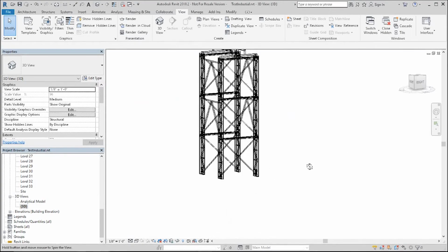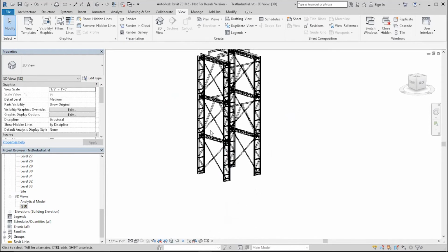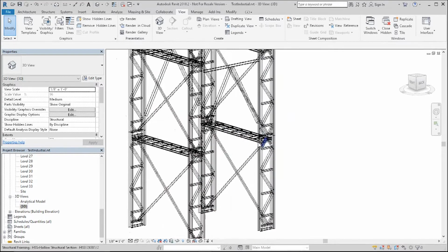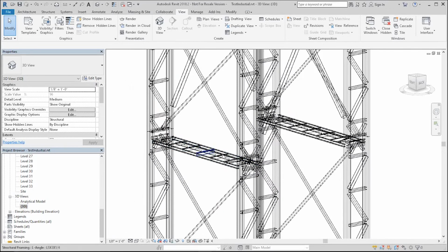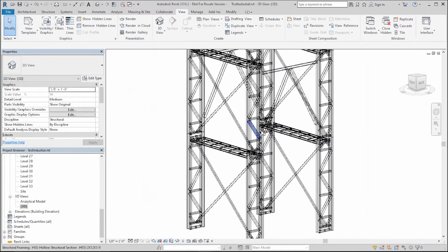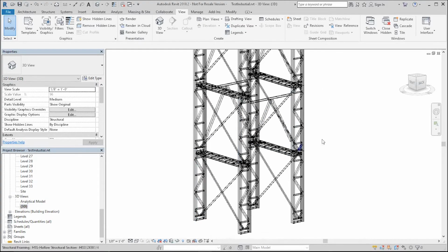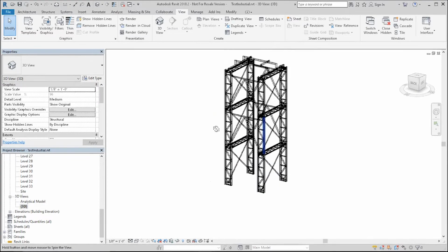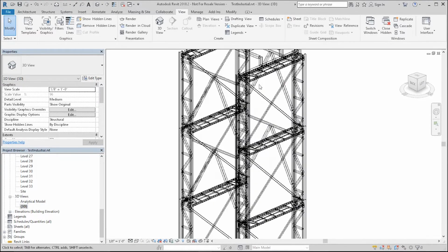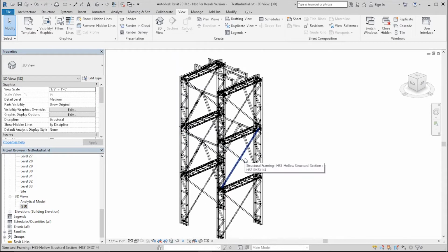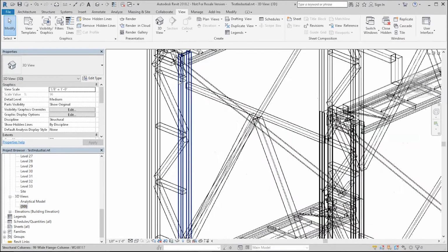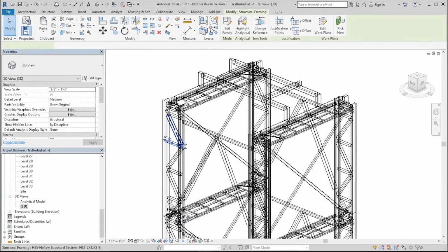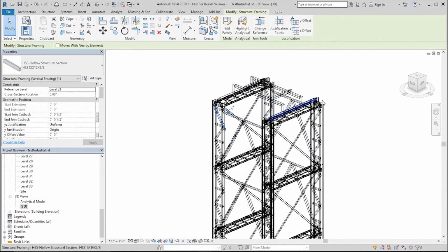I like this structure just because it's got a lot going on in it, and we can still see levels in it, but it doesn't have your typical, there's probably B deck on here. It's not really going to be what I might call a diaphragm. A rigid diaphragm doesn't really fit in this type of structure. So it really is a RISA 3D model when I look at it. I wouldn't take this over to RISAFloor, for example. I would struggle with it, because the problem is floor by floor. This would have some problems along the distances, since these wouldn't be on a floor level, and things like that.